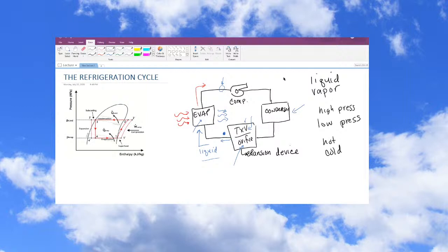It's 20, 30 psi, and it's all pretty much a vapor at that point. Then the compressor kicks on. What does the compressor do? Well, it takes that vapor and it starts to push it through the system. As the flow picks up, then this orifice here, the TXV, is shutting down, providing the most restriction possible in this line at this point.